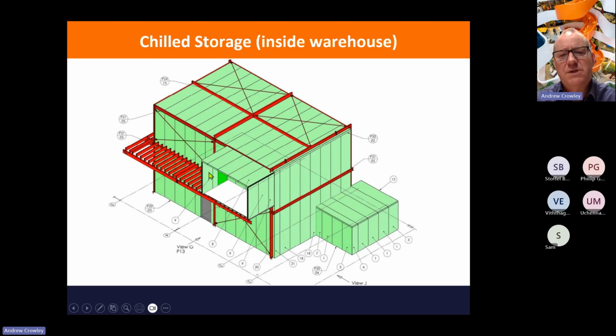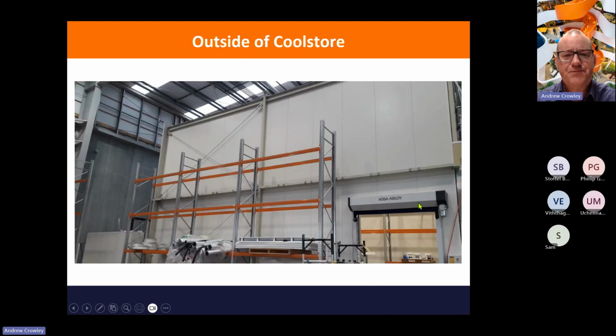It's a relatively small room, so this is basically a building within a building as well. Down here we have a freezer again, but it's quite small, so therefore it's entirely self-supporting. There's no structure other than the SIPS to support these small buildings. So this can be done when the size of the building is quite small.